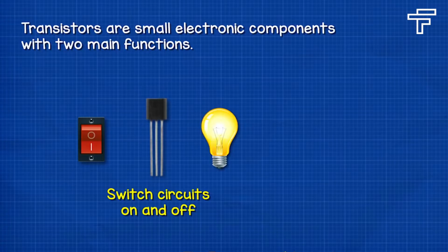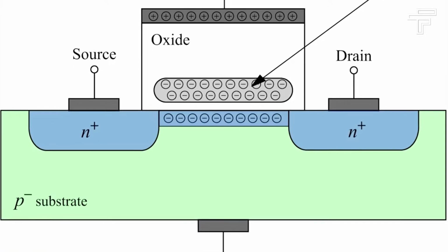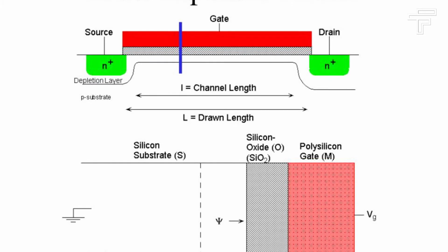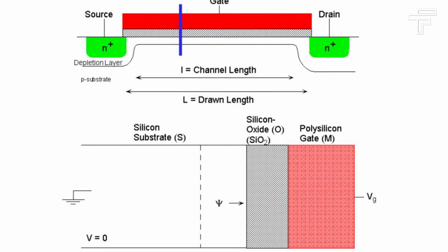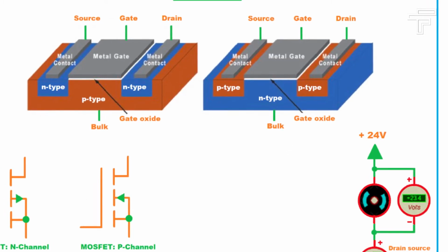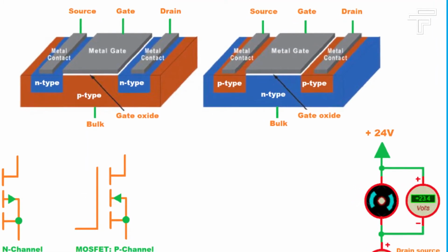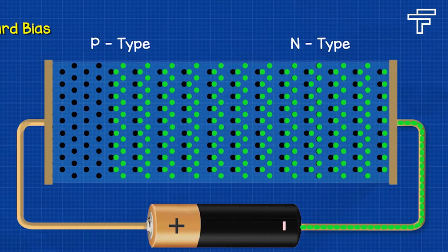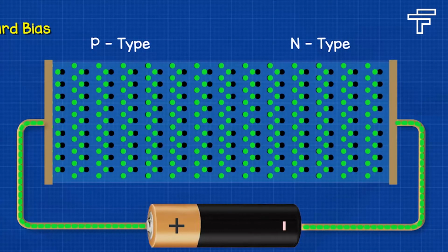The working of a MOSFET depends upon the MOS capacitor. The MOS capacitor is the main part of the MOSFET. The semiconductor surface below the oxide layer is located between source and drain terminals. It can be inverted from P-type to N-type by applying positive or negative gate voltages. This ultra-thin insulated metal gate electrode can be thought of as one plate of a capacitor.